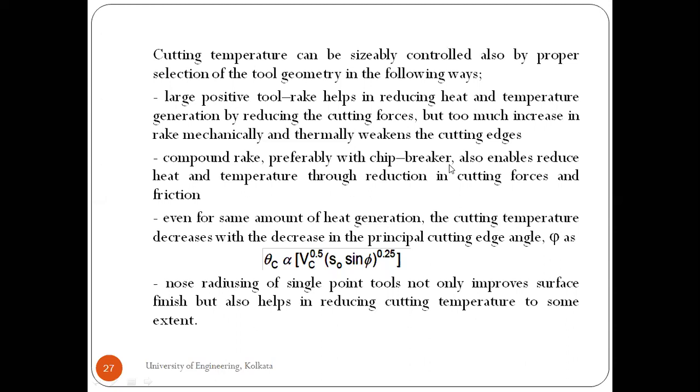Now, chip breaker, I told you once that chip breakers are used in case of ductile material cutting, wherein continuous chips are formed. So there is a chance of entanglement of the chips with the tool. That is not preferred, because the machining zone gets hindered and the chips which are coming out from the workpiece get entangled with the tool and the workpiece.